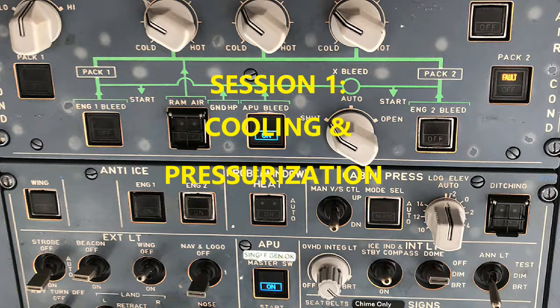So what kind of tests are there here? There are 3 tests involved: the system test, the continuous monitoring, and the power up test. The system test is done upon request on the multi-purpose control display unit, the MCDU. Typically that's done after you've replaced a part, then you run a system check. You guys know that. That's standard procedure.